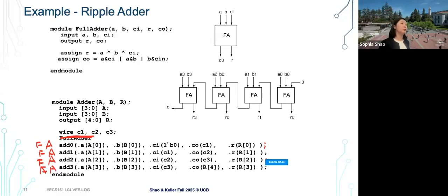So you basically instantiate 4 copies of full adders here. Does that make sense? Because we actually want to have 4 adders. If you look at the circuit here, we want to instantiate 4 adders. So all of them form from the same basic building block, but I want 4, and they need to actually exist.